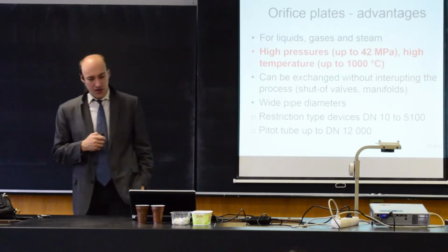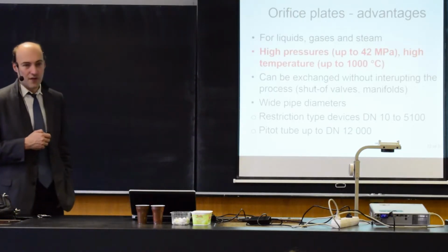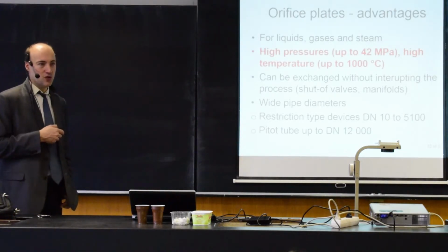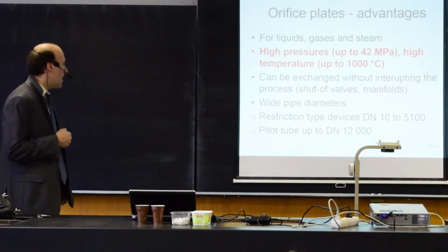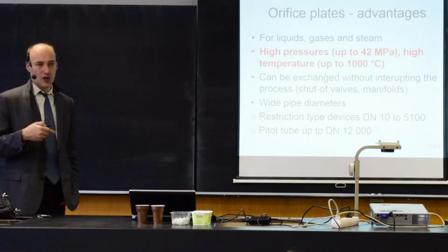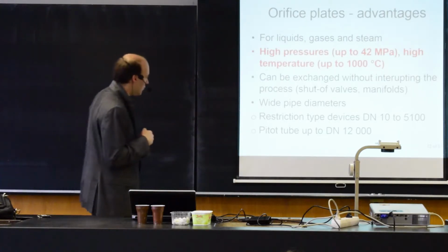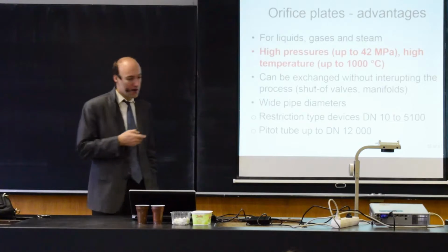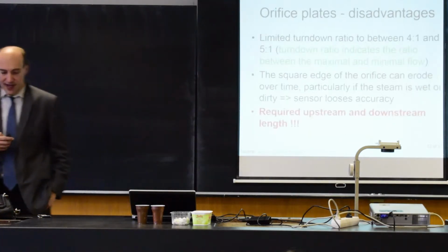For larger diameters, we are not using orifice plates, but we are using pitot tubes, which work in a little bit different way. But it's basically also the same principle that you measure the pressure and relate this to the flow rate. So those are the advantages of orifice plates.